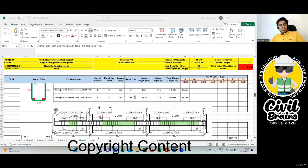Now that's it. You don't have to do plus 1, because plus 1 I have already done here. So I didn't do that. 48 number of stirrups are required. Cutting length remains the same. So total cutting length will be 1.376 into 48 into 1, which will give me 66.048. So again, under the 8 mm, this answer multiplied by 0.395 will give me this one. Finished. Done and dusted. Got it?